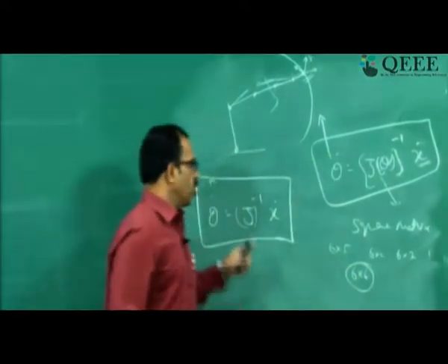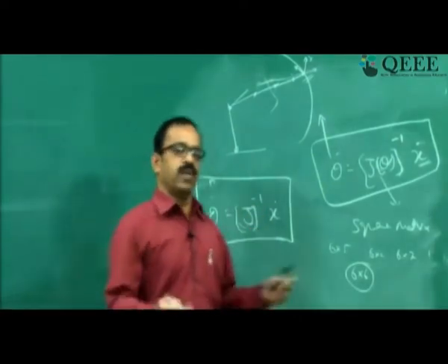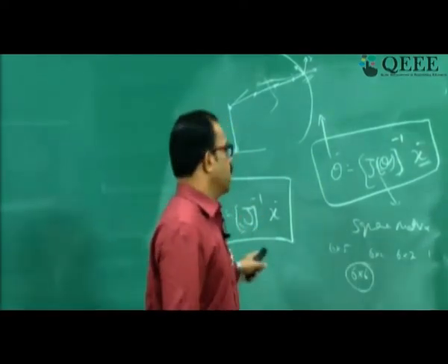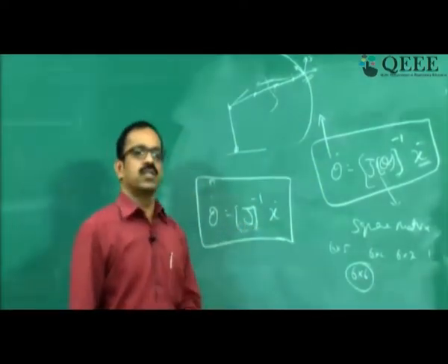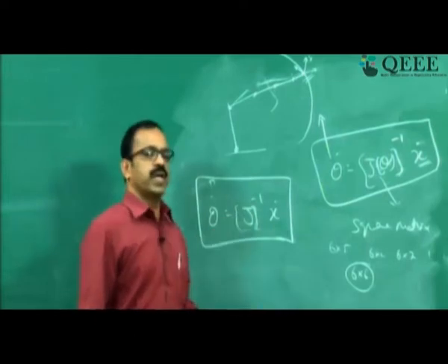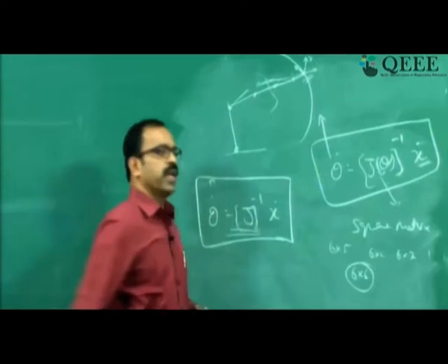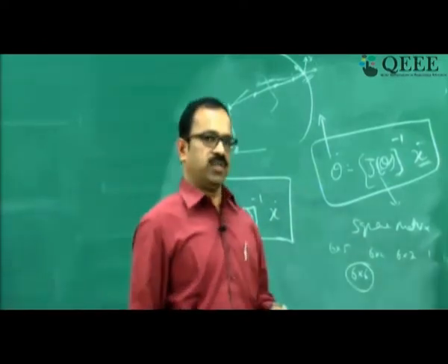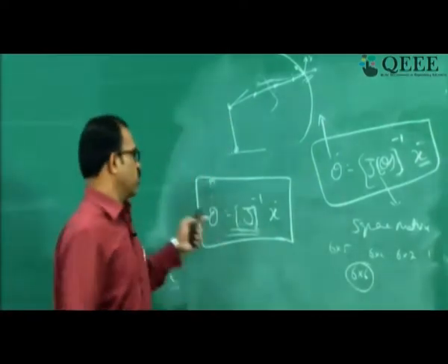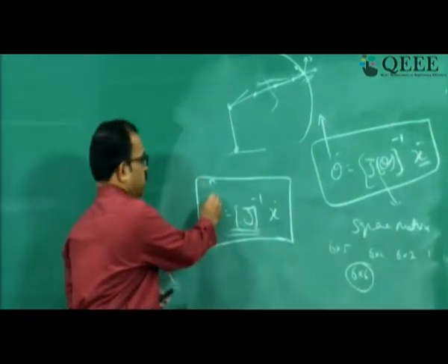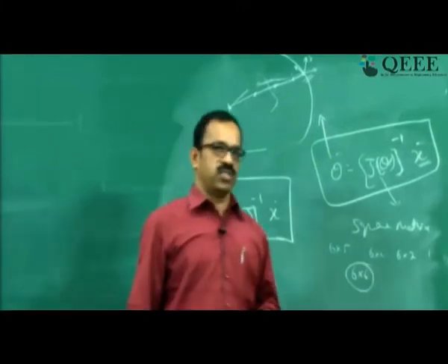So normally, if we have a manipulator with 5 degrees of freedom, or anything not equal to 6, we always have a matrix which is not square, and getting the inverse will be a problem for this kind of matrix. Therefore we cannot really get the inverse of J for practical applications. And this leads to a problem of calculating theta dots. For this kind of situation, we use something called a generalized inverse.